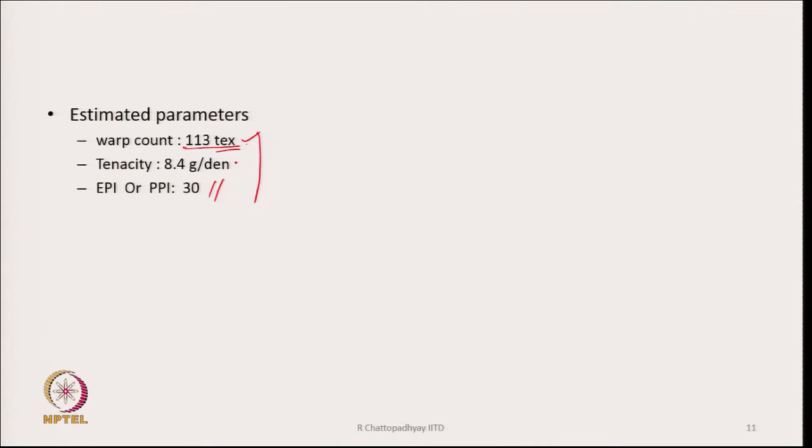So, whatever is available closest to these values, we have to choose that yarn from our inventory and then recalculate whether, if I use the yarn which is available, which is closer to this, it will meet the requirement of strength in both the directions, warp and weft, and whether it is going to meet the GSM requirement and the thickness requirement or not. Okay.